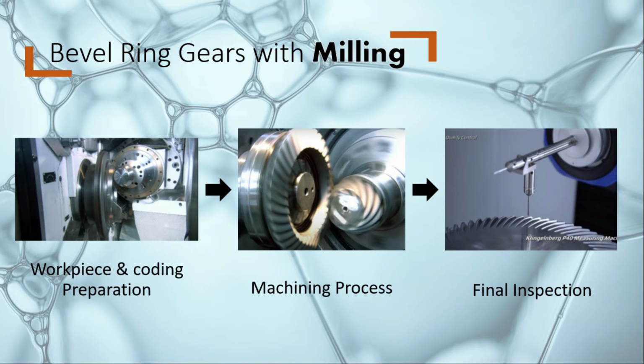The workpiece will be cut slowly, by 0.5 mm depth. In the milling of the bevel gear, they actually cut the workpiece. At first, they cut slowly to get the shape. Then after that, they cut 1 mm and 1 mm at a time. When the process is done, a mechanical meter gauge is used to measure the accuracy of the machining process, to find out which teeth have bad quality or bad dimensions and will be rejected by QA.